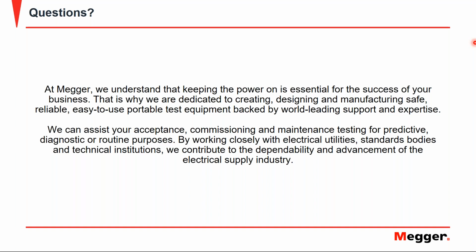it is incapable of finding, or in most cases it's incapable of finding, partial discharges or defects in joints which discharge on a low level. As it's an average of the entire cable, the Tangens delta diagnostics will not be capable of identifying that, and therefore it's not a tool to be used to plan your partial discharge diagnostics. So basically, both measurements are needed, where the Tangens delta diagnosis is only needed on aged cables, and on new cables, the PD diagnosis is recommended. So new cables, PD diagnosis; on aged cables, Tangens delta and PD diagnosis.